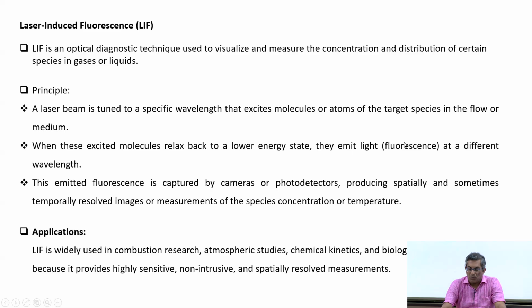But what is interesting here is that the fluorescence light that is emitted has a different wavelength than the incident light. So by using a suitable optical filter, you can filter out the incident light or the scattered light, and you capture only the fluorescence light. That is the basic principle of the laser-induced fluorescence technique.